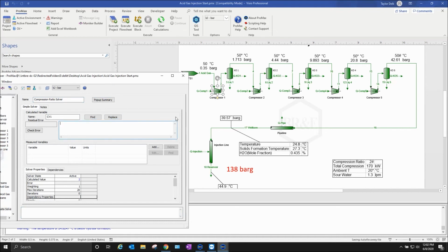And I'll say we want to come up with an error function for this iterative process to iterate on, a little guess and check. It wants to drive this function to 0. So every time the simulation executes, it looks at this equation and asks, is it 0 yet, or is it within 0.0001 of this? If it's not, it'll execute again. If it is, it will say that the simulation's finished.